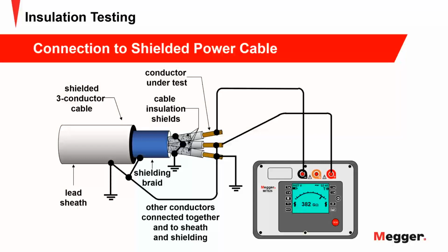Okay, so in the last few minutes, we're going to do a quick review of the properties of an insulation tester and what you might want to look for. So we'll look at the guard terminal first. This is an example of a two-terminal test setup where the industry standard is negative to circuitry and positive to return. Here we're looking at phase A, for instance, and how it relates to all your other phases and ground. Next.